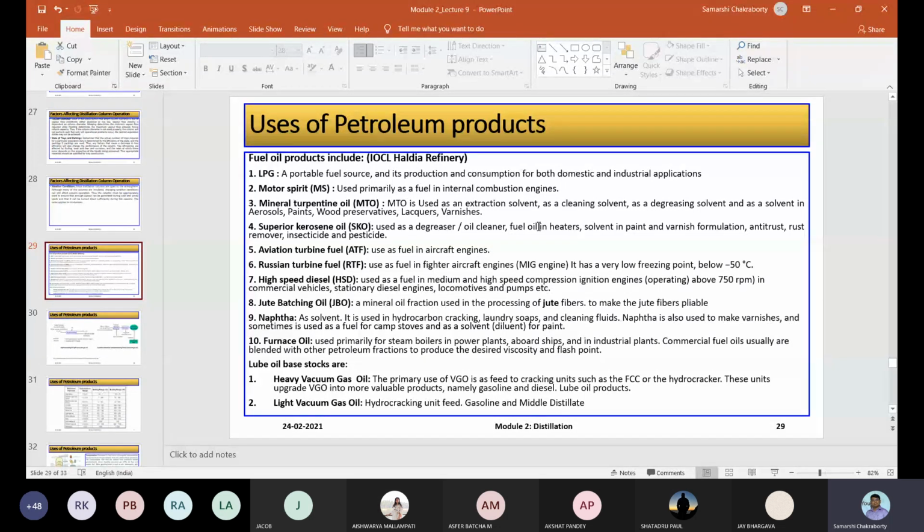If my pour point is not low enough, then at that very high altitude, where the outside temperature is -40, -50 degrees centigrade, the turbine oil freezes out. You can consider the devastation it can cause. The plane is going to crash.